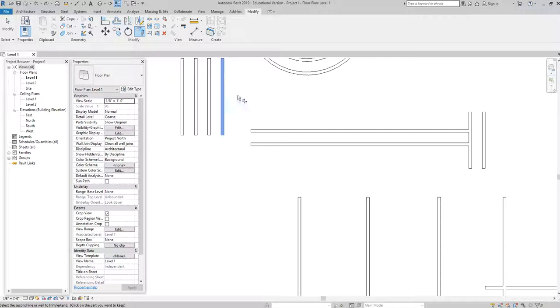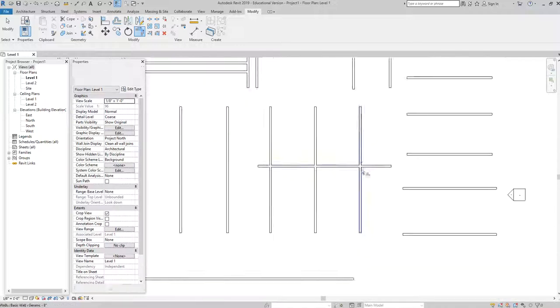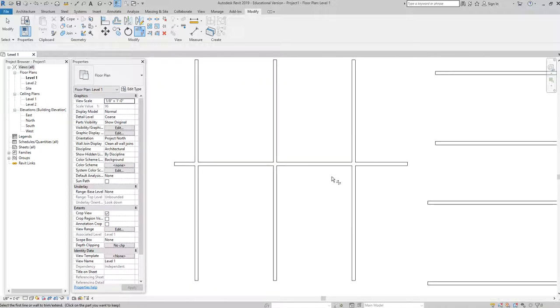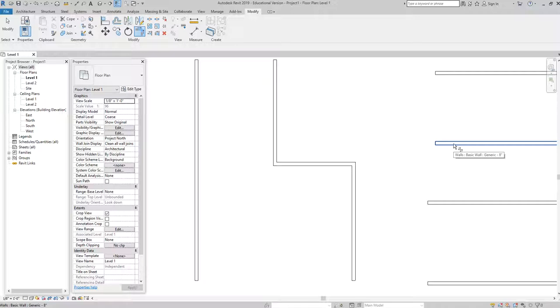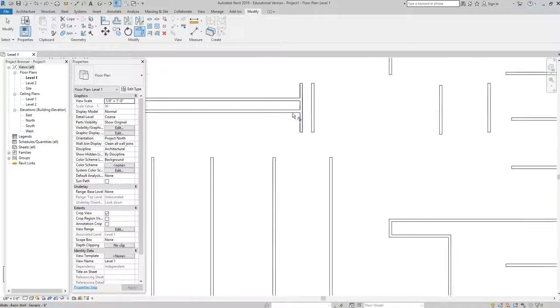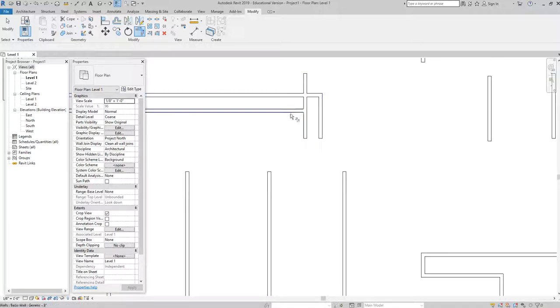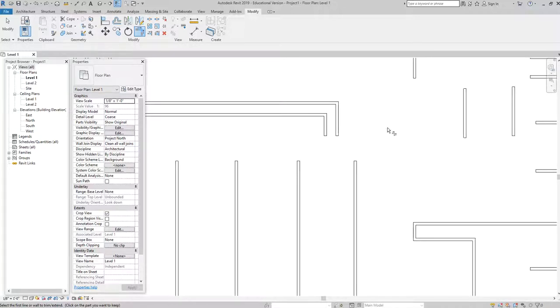So click one, click two, trims them off. Those had to extend. But what happens when these two things extend past one another and I want to trim them off so they're clean in this direction? Click, click, trims it off that way. Click, click, trims it off that way. Click, click, trims it off that way. This one will extend. So it either extends to create a squared off corner, or it trims off pieces it doesn't need to create that squared off corner.